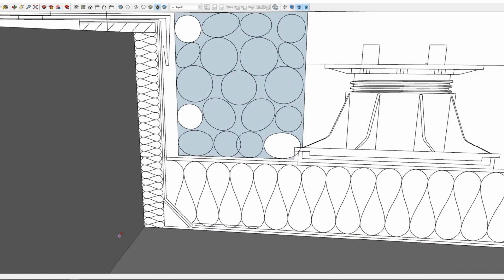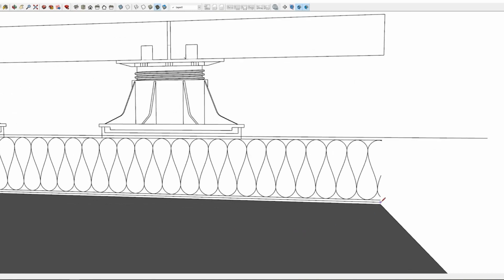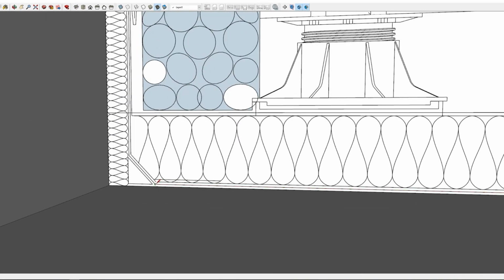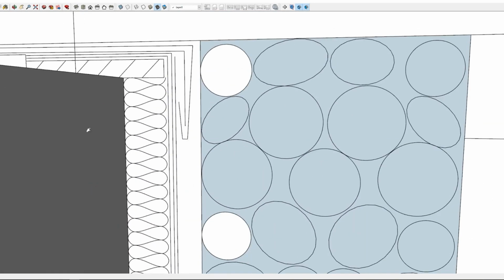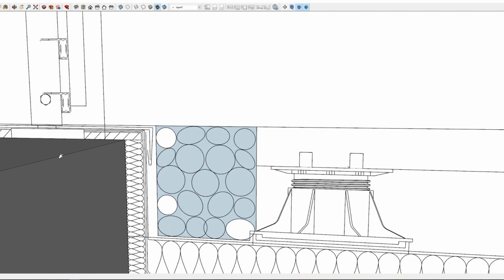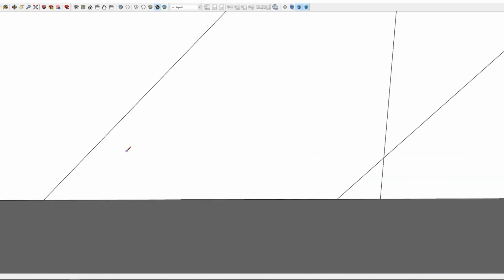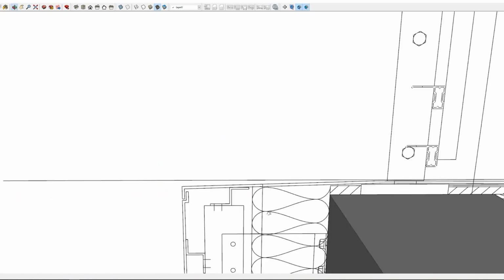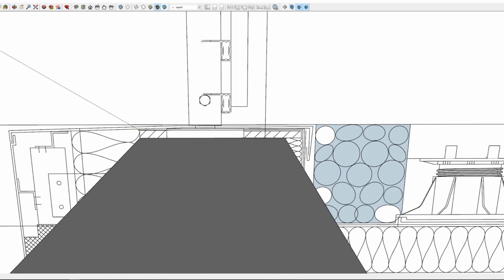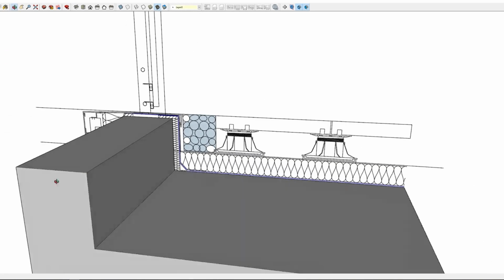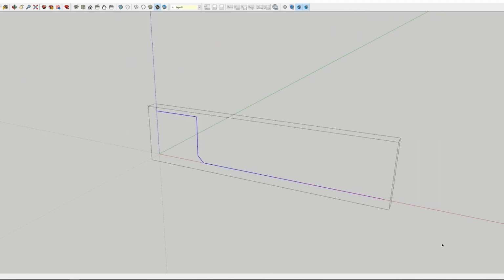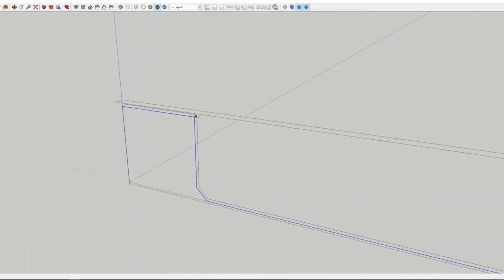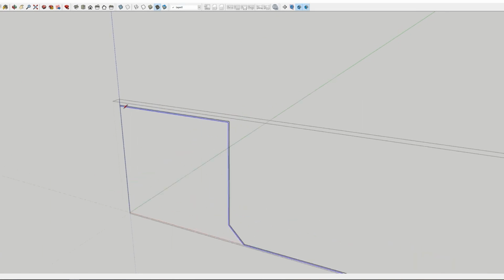So then, with the membranes, what I was talking about, you've got your main waterproofing one that works its way up and across the upstand there. It probably wants to go a bit further than that. Actually, you want to go right to the edge of the upstand there. Right now, it'd be tough to draw the thickness on that, so I'm just going to draw it as a line, and then dive into the groove like that, and then give it its thickness in here. So 2mm.